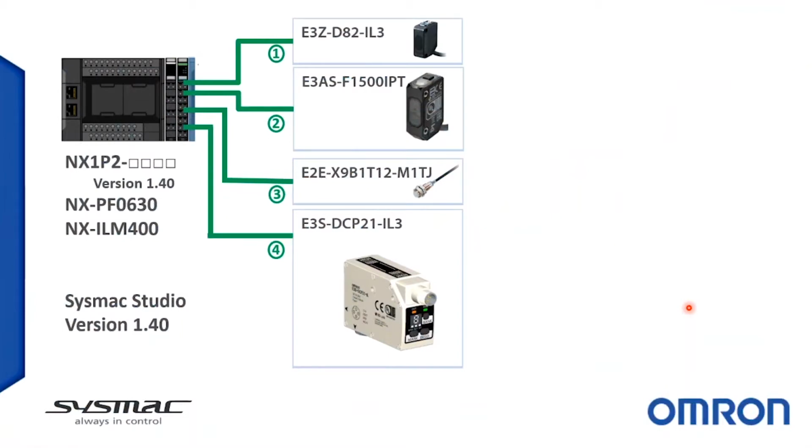During this video, we'll see a feature introduced with SYSMAC NJ and NX series controllers version 1.40 to simplify the setup of IO-Link devices with SYSMAC Studio. I have an NX1P controller with an NX ILM400 4-port IO-Link master unit. Connected to the ILM400, I have a selection of IO-Link sensors: E3Z and E3AS photoelectric sensors, an E2E Next proximity sensor, and an E3S color mark sensor.